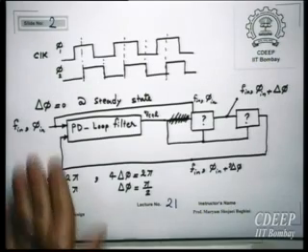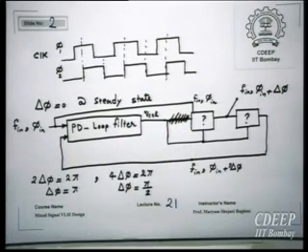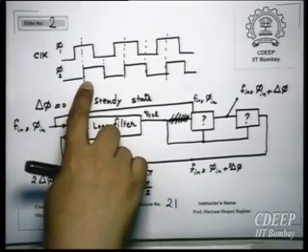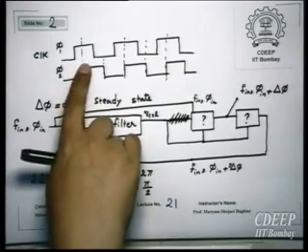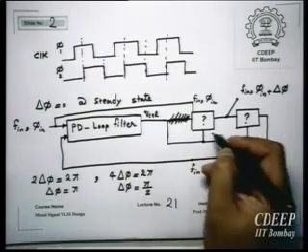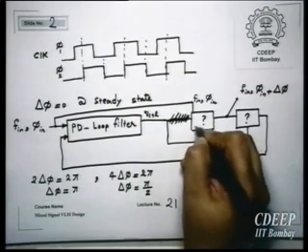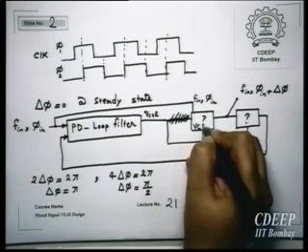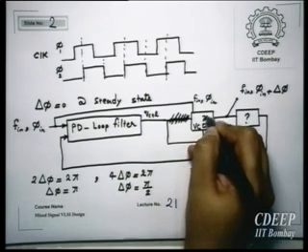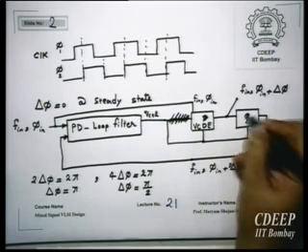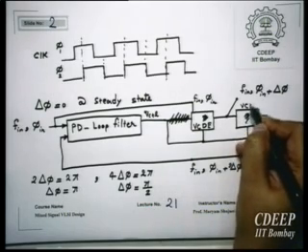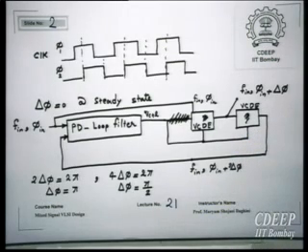If you consider the input signal is a digital clock, effectively I want to generate a phase shift. What does it mean? It means that I want just to generate a delay. Therefore, this is nothing else other than a voltage control delay element. So this will be a voltage control delay element, because making a phase shift in the digital domain is simply making a delay.